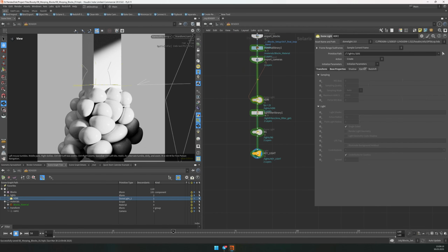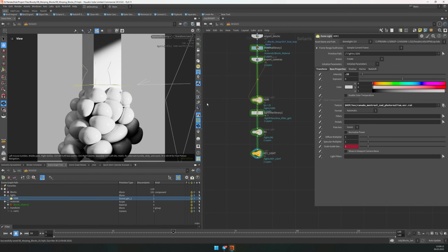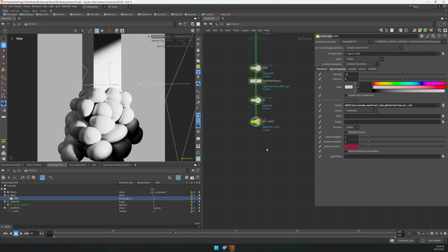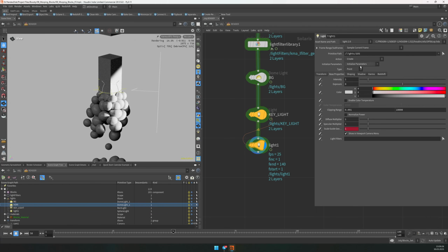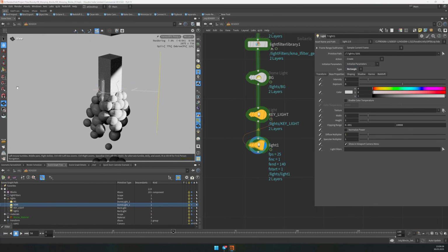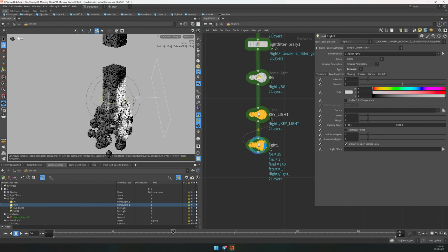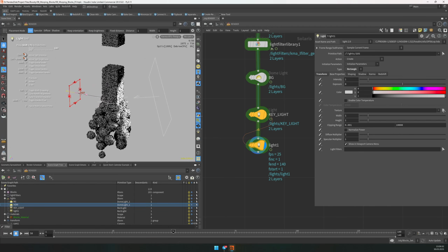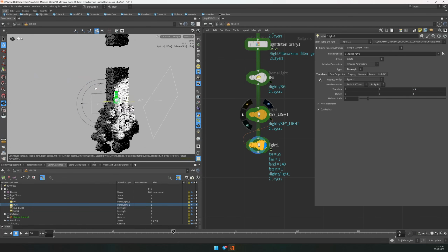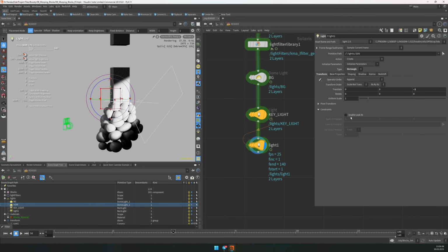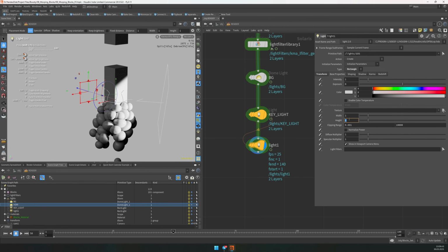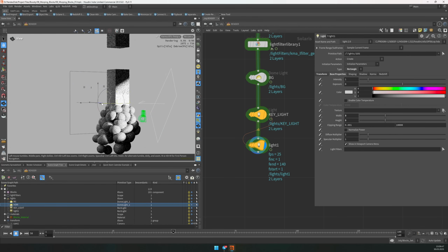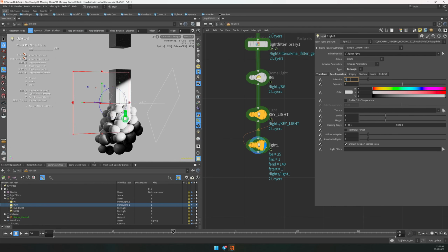The other thing we need is some nice rim light here. Let's lower this HDR a little bit more, and let's take another light. Let's also switch this to a rectangular and put it back a little bit. This doesn't need to be constrained, but you can still make it look at constraints. Let's increase the height and the width as well, and let's increase the intensity.